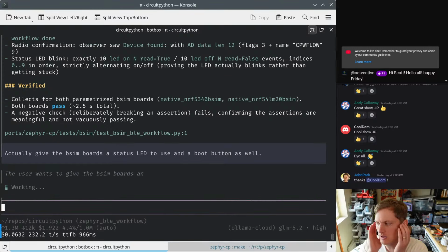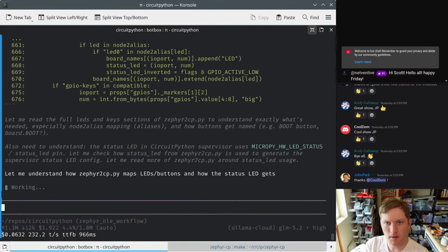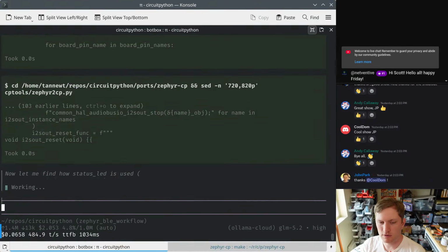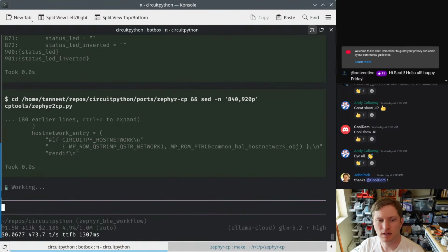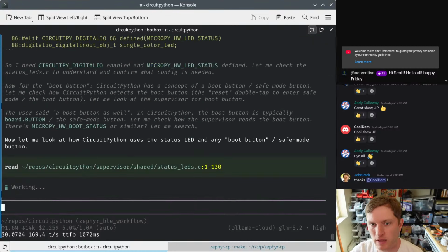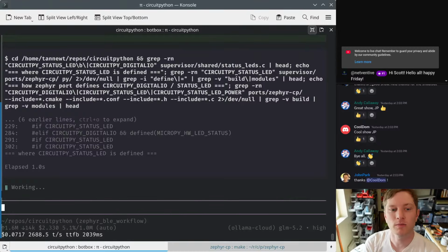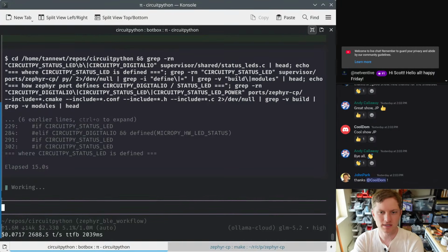So the way that the BLE workflow is supposed to work is that you start up, and if you're bonded, so if you've connected to something previously, it will just advertise privately in a way that only that device will know who you are and what it's doing. Otherwise, you'll enter into this public advertising mode, but you have to do that by pressing the button when it's fast blinking. This is so that you're not always in this mode of bonding and pairing. It's kind of like a discoverable mode. And so that's the first step that I want to see tested here.